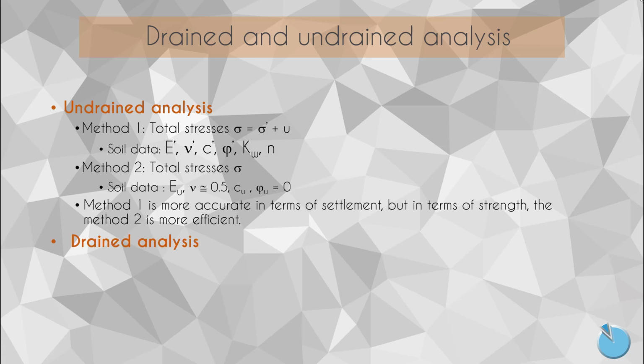The second case of semi-coupled analysis is the drained analysis. There, no variation in the pore pressure field occurs, so the total stresses variation depends on the effective stresses variation. We use the drained soil parameters.